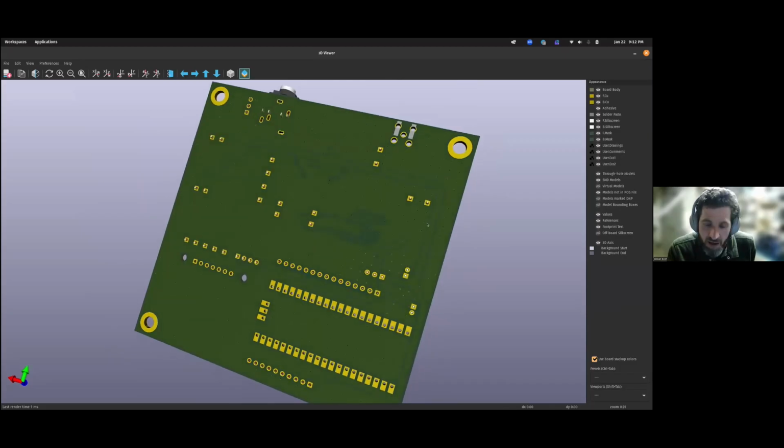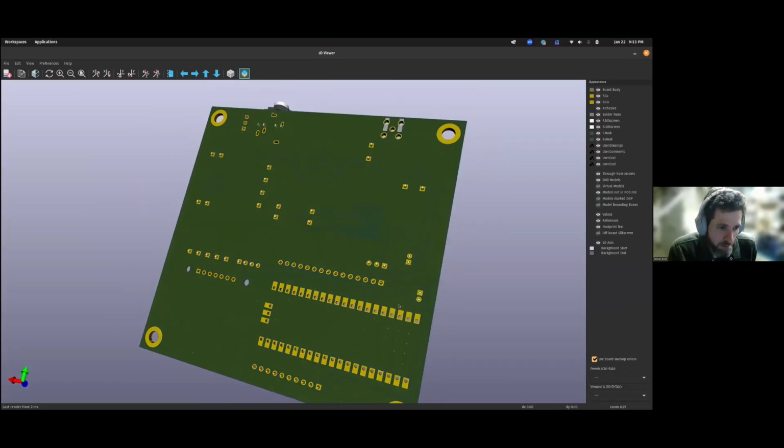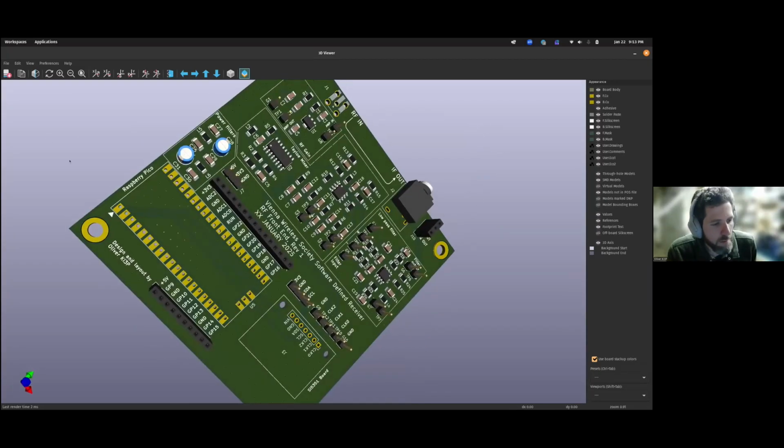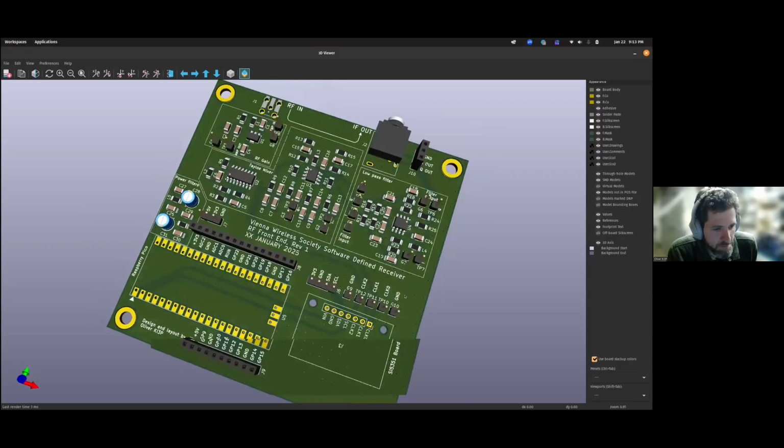They don't need to be that wide for the current that's been drawn. This is going to be a low current circuit, but it just reduces the inductance of those transmission lines. The wider they are, the lower their inductance. So anyway, it makes life a bit easier.